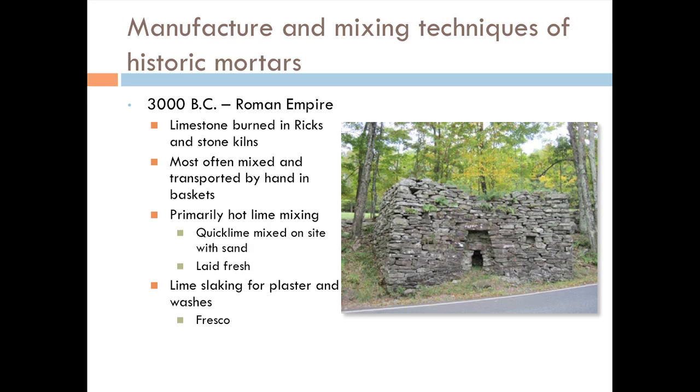They'd also use it for plaster and lime washes to freshen up an area for cleaning, because lime will reduce the amount of mildew, and it's antibacterial. Over in Europe, I came across a recent document from what would be the equivalent of their CDC, Center for Disease Control, and they recommend whitewashing your barns to protect from H1N1. It's because of its alkalinity, its pH level, which once it's cured is around 8, can go up. But when it's fresh, it's around 11.